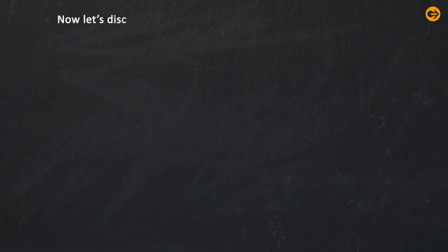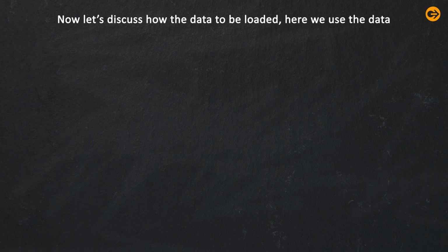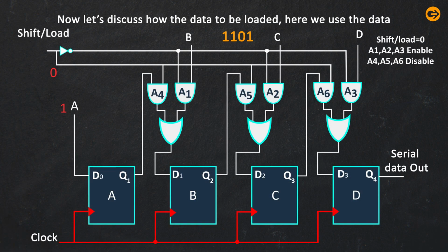Now let us discuss how the data is loaded. Here we use the data 1101. We apply the control signal as 0. The output of the NOT gate becomes 1, which is load mode or active low. Then all the inputs are loaded to the outputs of the AND gates A1, A2 and A3 because they are enabled, and at the same time all the OR gates are also enabled, as shown in the figure. Then that value is loaded here. So when the control signal becomes 0, the data is loaded to the inputs of each flip-flop.